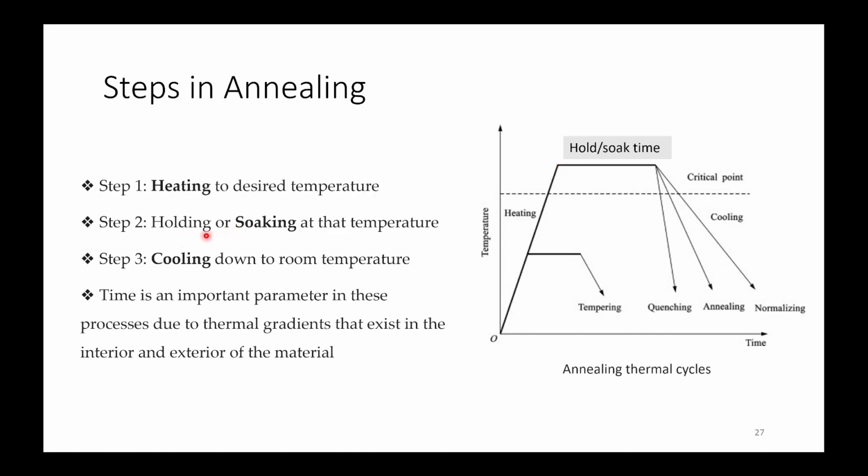It is held here for some time, which is known as hold time or soak time. So holding or soaking at that temperature, then cooling down to room temperature. This holding is done so that the temperature reaches a particular temperature uniformly throughout the specimen, and then cooling down to room temperature.